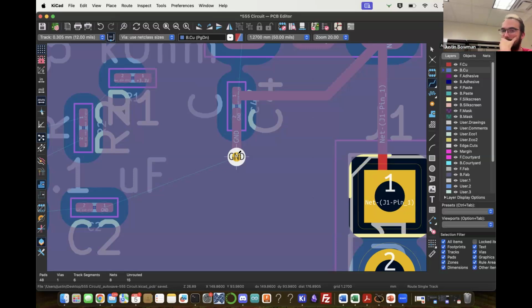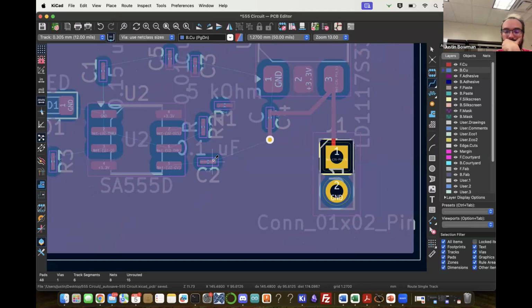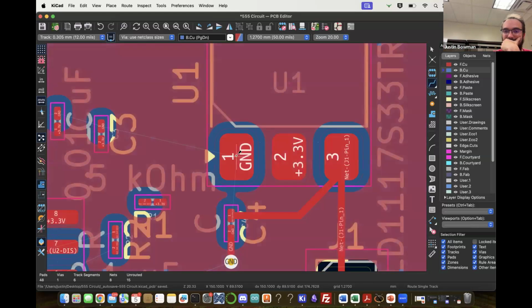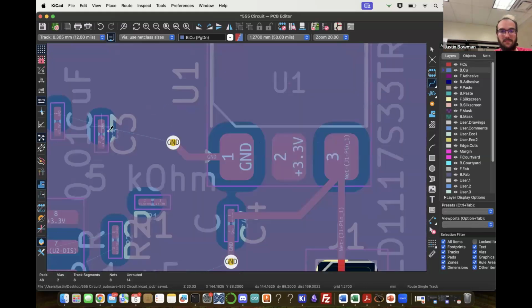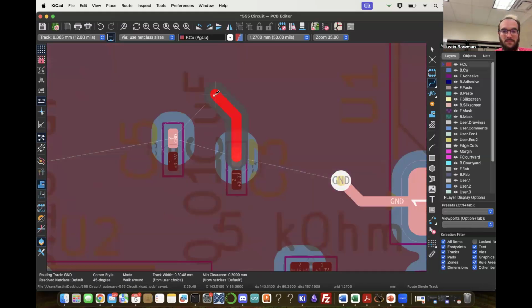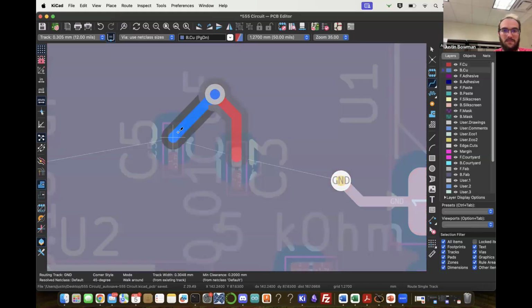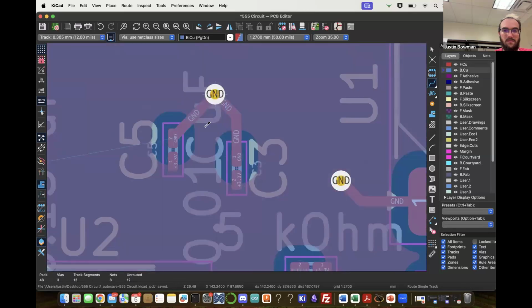Yes, so the Innovation Hub is potentially something we want to do after this training, once everyone has designed their own PCB. What they will do is you get a double-sided PCB, you etch whatever you have on both sides, and it will drill the hole for you. Then you take a small rivet, put it in there, and punch it.